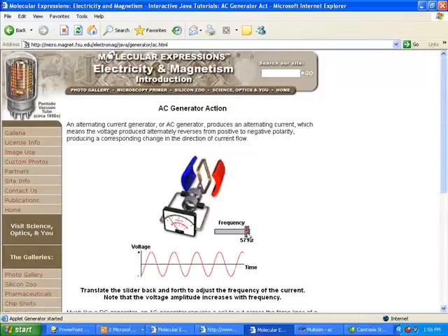If I crank this way up, you can see it's almost pegging the meter going both directions. And that's a principle of AC generation, that the coil must be moving in the magnetic field to generate a voltage, and the faster it moves, the larger the voltage it will be generating. This is because the coil is cutting more magnetic flux lines.